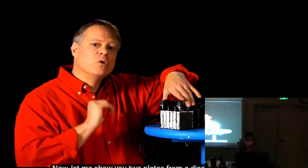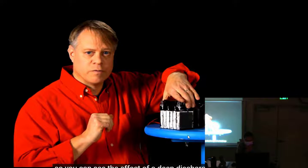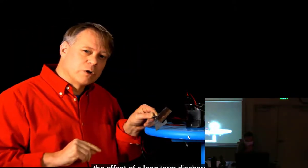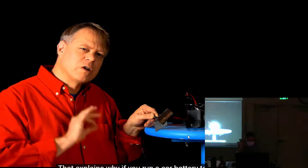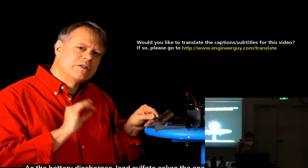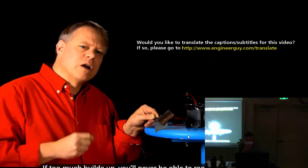Now, let me show you 2 plates from a discharged battery so you can see the effect of a deep discharge of a battery. If we look at these 2 plates, we can see the effect of a long-term discharge. This light coating here is lead sulfate. That explains why if you run a car battery to 0 charge a few times, you're likely to kill it. As the battery discharges, lead sulfate takes the space between the plates. If too much builds up, you'll never be able to recharge the battery.